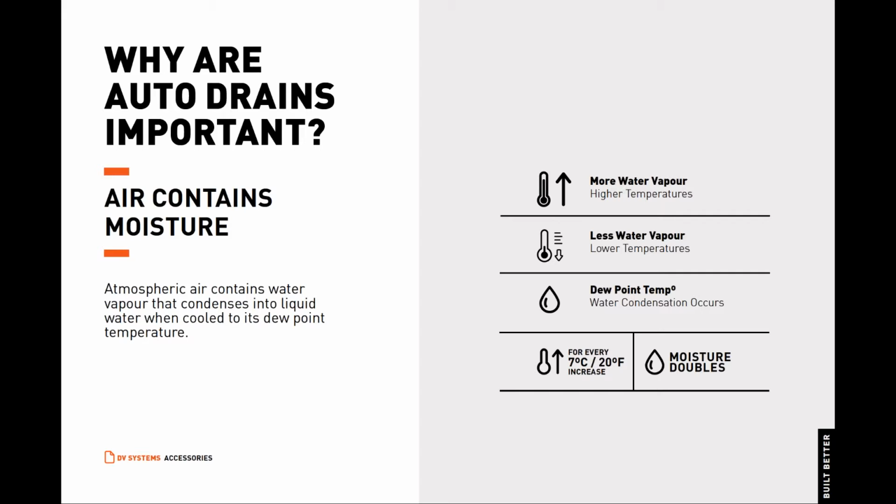Air compression generates a considerable amount of heat, and the compressed air discharged from an air compressor is relatively hot. As this hot compressed air travels through the distribution system, it cools down and moisture is condensed into liquid form, finding itself in the air receiver, air system piping, air filters, and point-of-use equipment and tools. Drain valves are crucial components of a compressed air system.